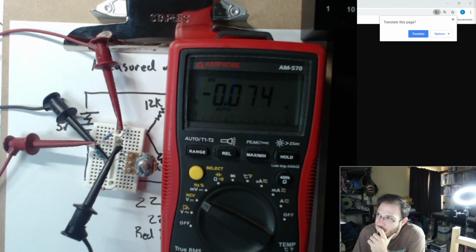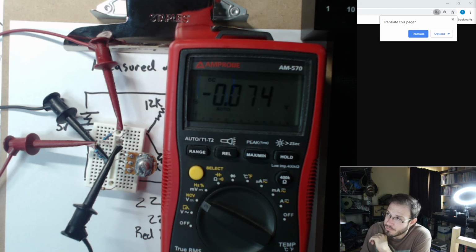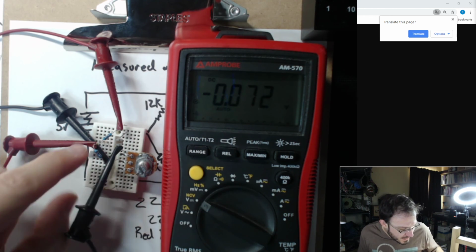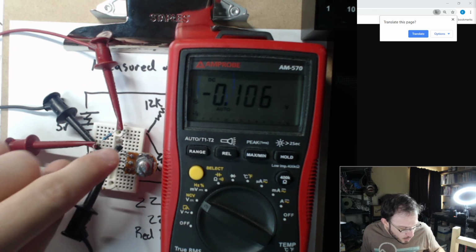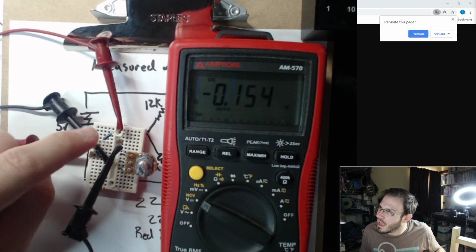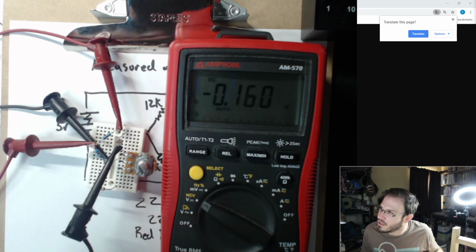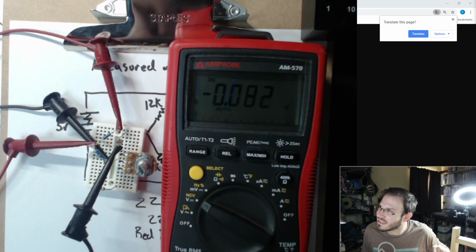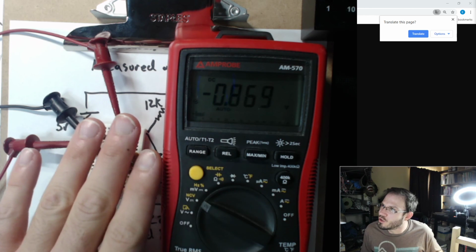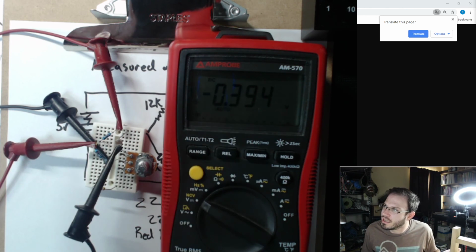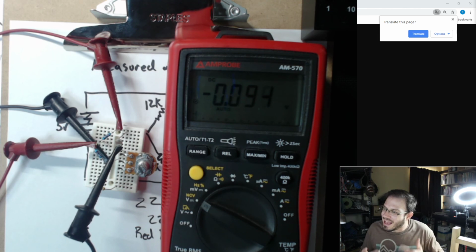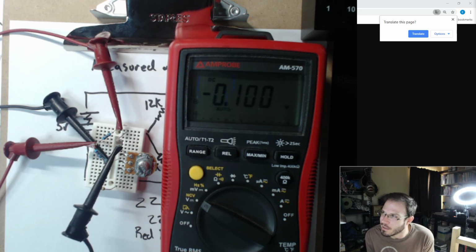Another great benefit of our Wheatstone bridge is resistance changes with temperature. Well, since I'm only measuring the ratio between my two voltages, as temperature goes up, these resistors change their resistance slightly as well. So we can assume that the whole system changes temperature at the same time. That's going to help to negate some of those temperature effects of our sensor circuit.